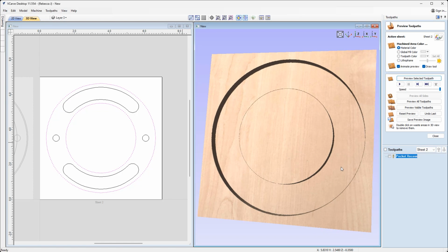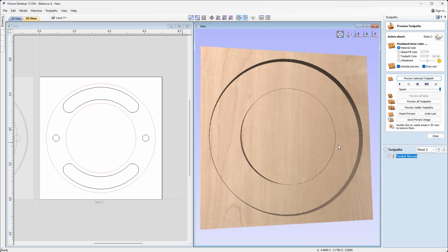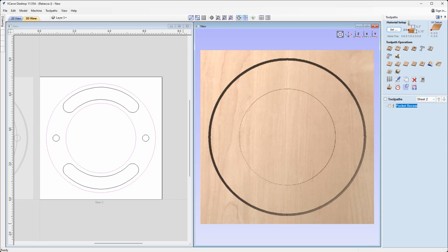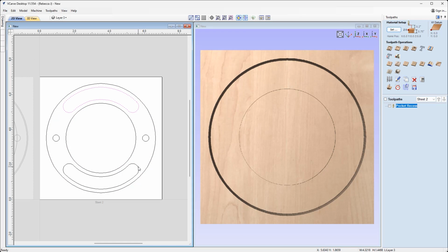So here I've cut down by 0.35, and so I should have 0.4 left over here. And then from there, we're going to create our recess tracks for the marbles along with the actual magnets as well. So let's go ahead and press close out here. Now let's take this vector here and this vector here, and then we're going to go into the pocket toolpath.